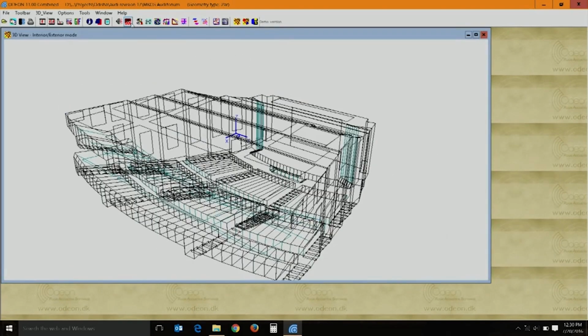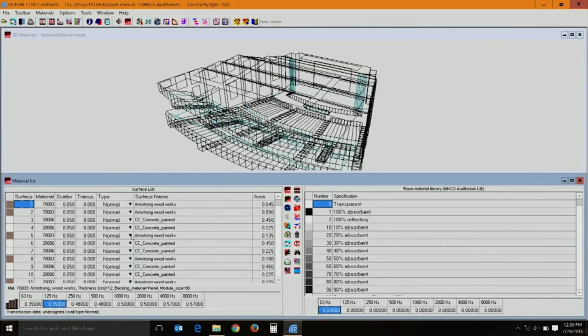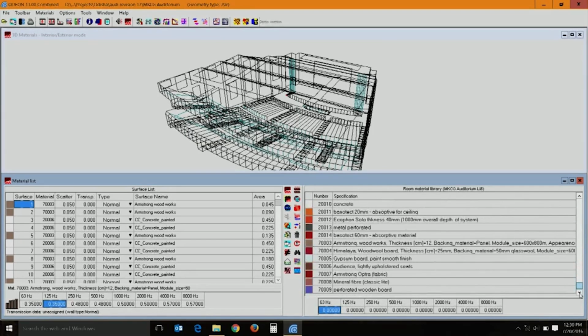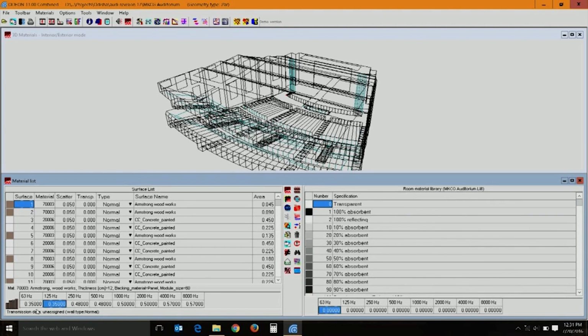The next part here is, first, to make the drawing itself, the physical dimensioning and drawing. Making the drawing is the first task; I am not demonstrating the tool here. Next comes the material specification. If you take a typical material, we are going to talk about absorbing materials later. Depending on frequency, you see in this left hand corner there is a material library from which we can choose or add materials.